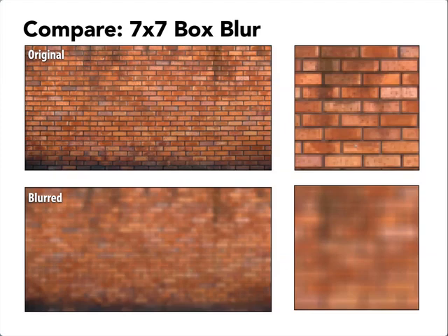So the 7x7 box blur results in averaging every 7x7 block, 7x7 neighboring pixels, to calculate an output pixel value at the corresponding location in the output image. So it's going to blur more than if we run just one 3x3 box blur, because if we ran one 3x3 box blur, we'd only average 3x3 neighboring values, right?